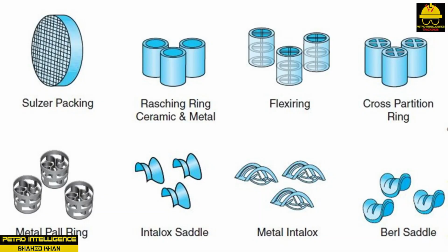Packing. The packing used in a distillation column provides the heart of the operation. Inside a distillation column, packing is either random or structured. Typically, a combination of both is used in a packed column. Random packing may be dumped into a section of the column or carefully stacked. The random spacing of the packing or areas between the packing gives this section its name. Structured packing comes in preformed layers that overlap into a single unit. The uniform spacing between voids characterizes the functionality of this section.